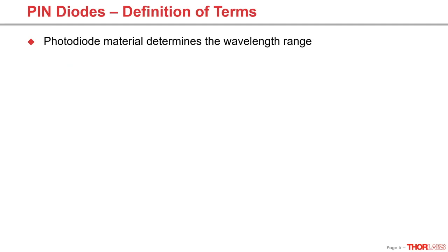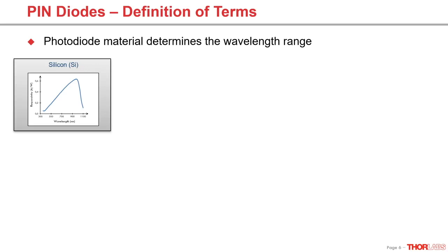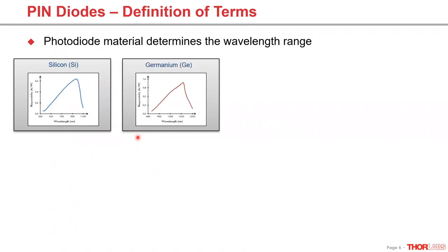So now coming back to our first question about the operating wavelengths. For all applications with visible or near-infrared lasers, a silicon photodiode will be the best choice. These are cost-effective, even with large active areas, and can be used from the UV up to 1064 nanometer laser wavelengths.